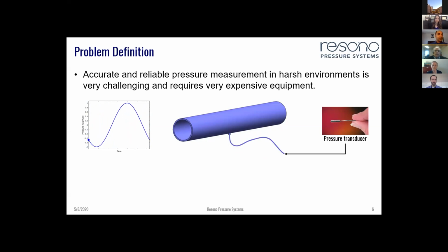By the time we have reached a point where we can put the pressure sensor in a location that is safe, our measurements are completely gone, right? What we were interested in is very distorted, and we can't use it anymore because it's not representing that blue signal, which was the true pressure variation inside the pipe.